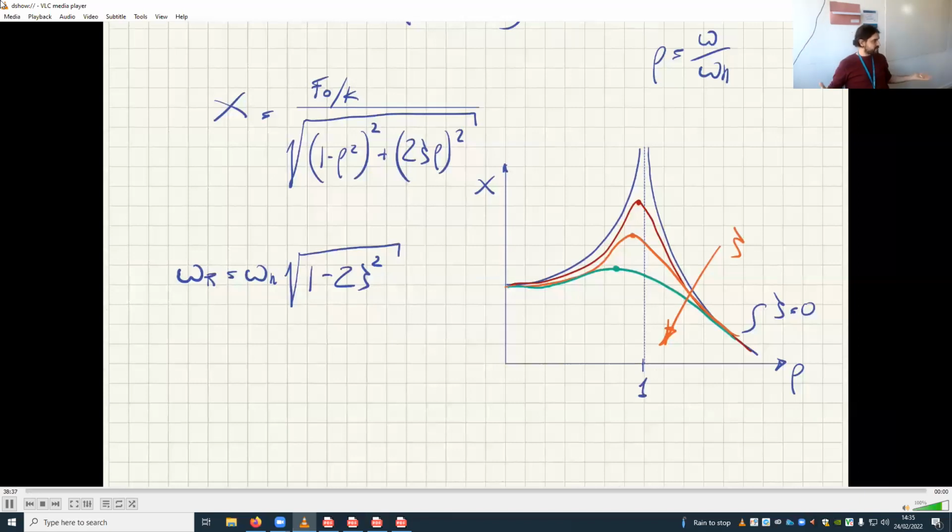So resonance is something that has to do with external factors, external agents. Sometimes we say, oh, that's the resonance frequency of this system, but this should be the natural frequency of the system. That's the property of the system. As long as you have mass and stiffness, you have a natural frequency.